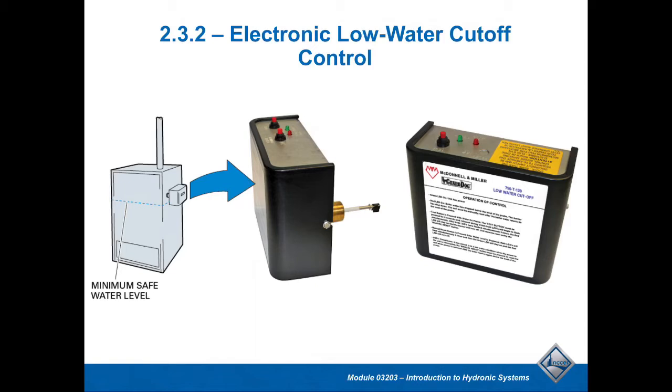But I don't particularly care for that as a main boiler Aquastat generally. I've seen them used on jobs, and I don't think they generally work very well for controlling and limiting the boiler. I think most boiler systems, you definitely want to have something that's directly embedded into the boiler to safely control that boiler temperature. So let's take a look at the next one here.